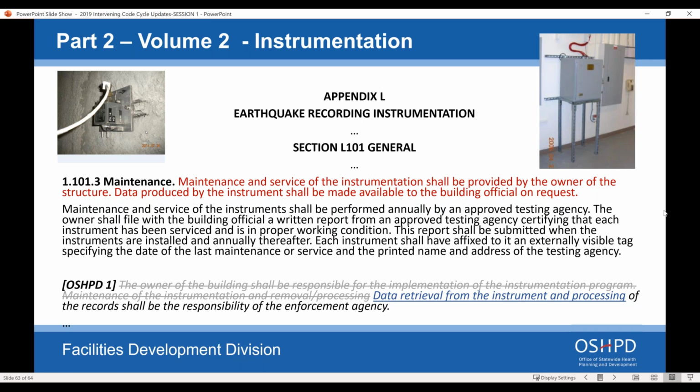Depending on your building, if it requires an AMC, an alternate method of compliance for your structural lateral force system, then you are required to instrument the building. If it is required instrumentation for that specific lateral force resisting system for that particular hospital building, then the